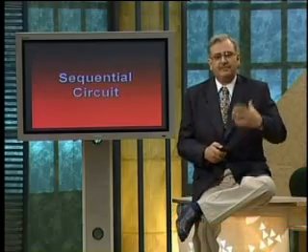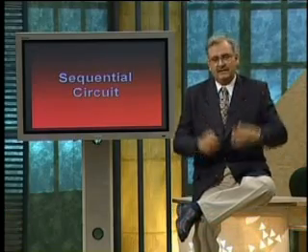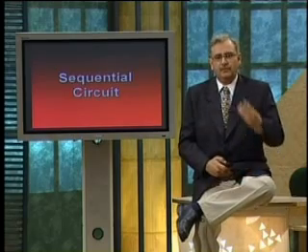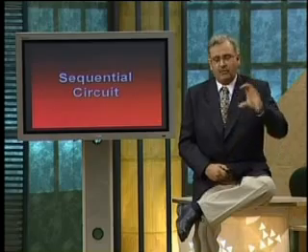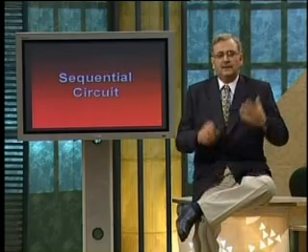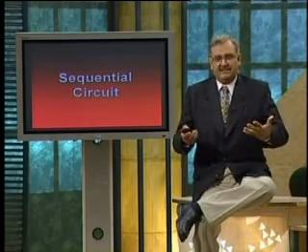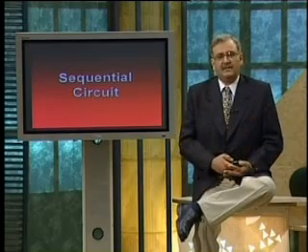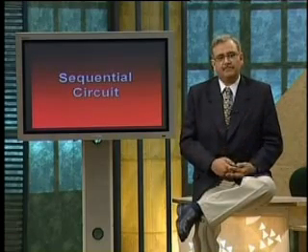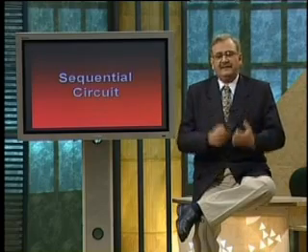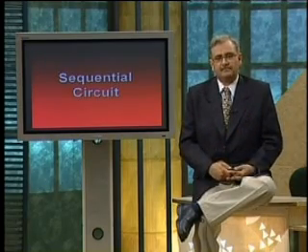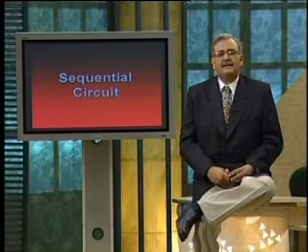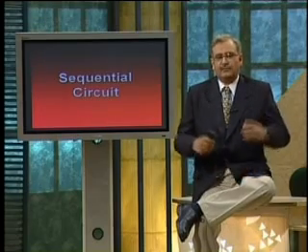Instead of having 3 different ICs, maintaining an inventory of 3 different ICs, we only have a single PLD device. So the cost goes down. PLD is flexible. You can implement any combinational or sequential circuit. The design time and the implementation time also reduces. We would be talking about PLD devices in the course.